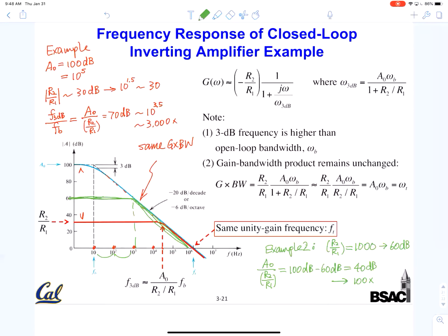It has the same gain-bandwidth product. I cannot go beyond that. I cannot, out of this op-amp, design something with 60 dB gain and megahertz bandwidth. It's just not possible. Towards the end, we'll talk about how to do that, okay? Basically by choosing a higher bandwidth op-amp, in short.